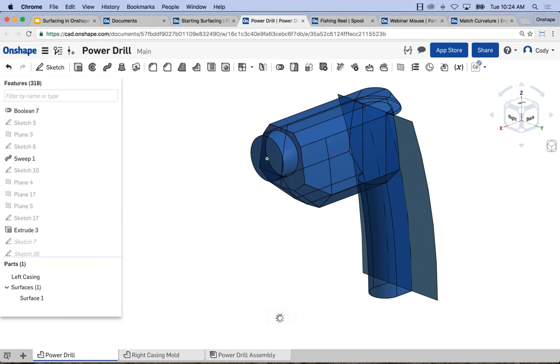I can hide them. I can delete them. You can delete them, by the way, and it will not break, so to speak, the model. It does a delete part very similar to deleting a solid model. But just keep in mind that you can create these surfaces that are just there for end conditions. Or, we know a lot of users out there create a surface just to define the depth of their thread, for example, because they like controlling it that way.